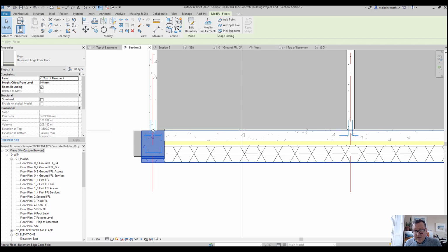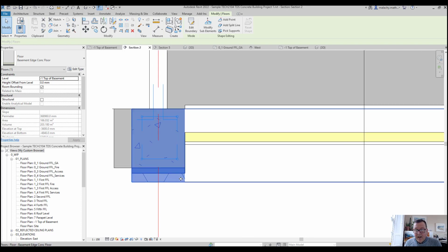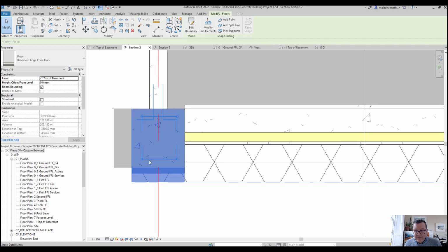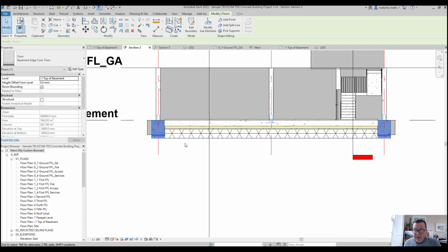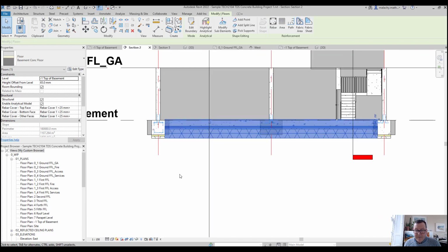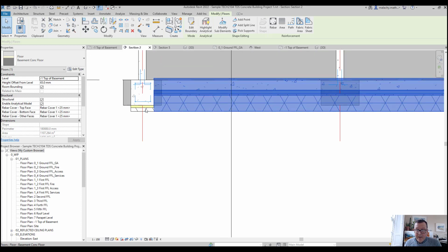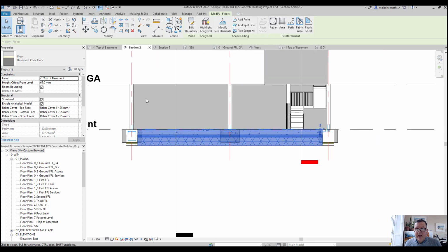And you'll see that that's placed directly underneath the center of the columns, because all the columns will be coming down here and the point load will be arriving in down here. And then roughly that's how the reinforcing will be done. It will be a cage in here, and there'll be starter bars going up there, which will start off the columns. All right. And then you see this element here is another floor element, and you can see I've designed it so that they kind of match up here in terms of the hardcore and things like that as well. And that slab there is 400 deep thick.